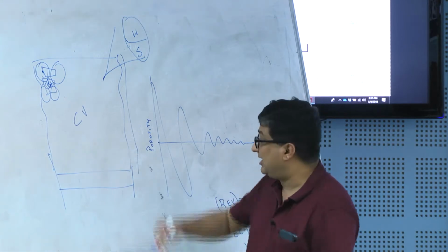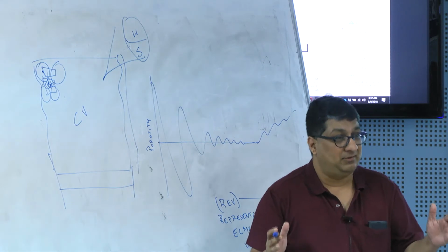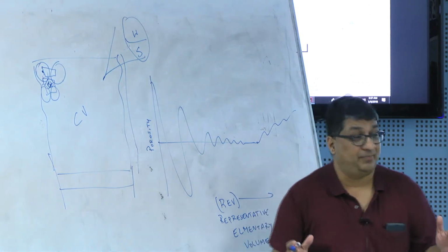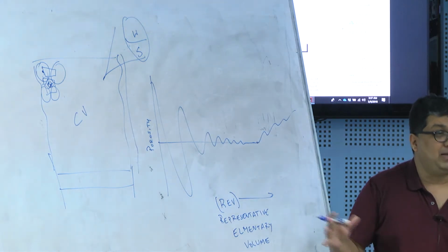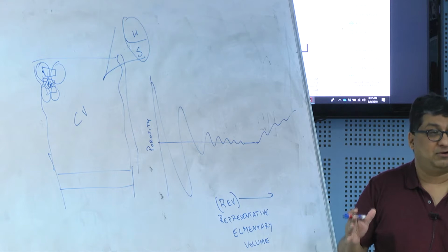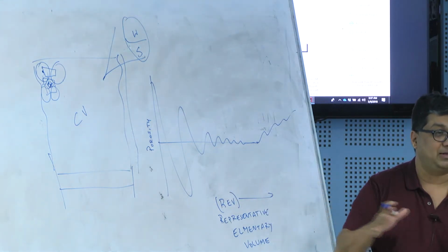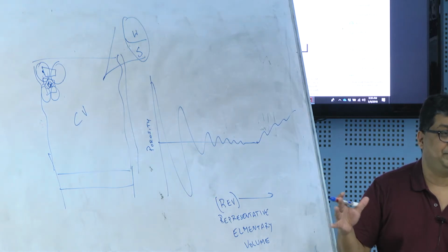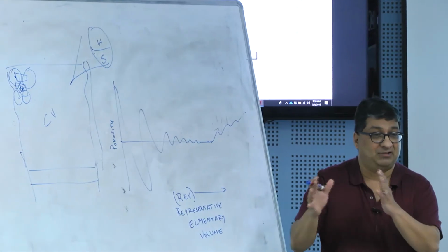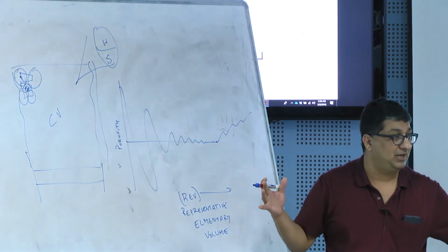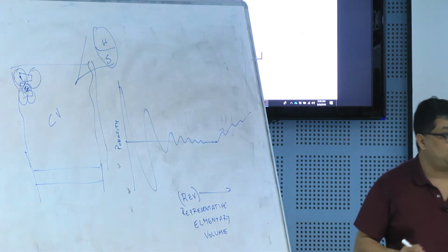So my porosity fluctuates a little bit till I hit some reasonable volume where it starts to become constant. Okay. If I start making this even bigger, I will start looking at not a relatively homogeneous media, but at relatively heterogeneous media. Okay, I might have sands and clays or very different geologic units. I may start sampling very different geologic units. So my averaging might cause my porosity to start fluctuating again.